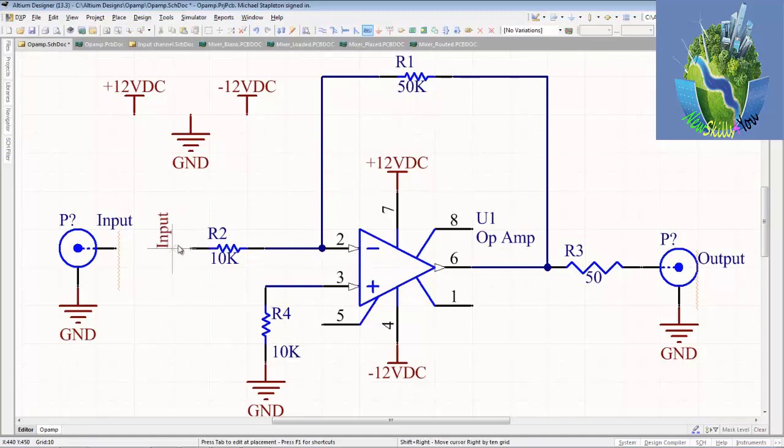See the little red X again? I put my net label on the connection, and I'll put it here. It's on the connection. Now that this node and this node have the same net name, they're electrically connected. That saves me from putting a wire across. Sometimes in your schematics, if you have too many wires, it can get confusing, makes it a little harder to read. Let's place one more connector and then we'll update.